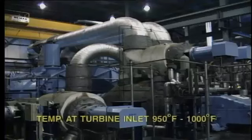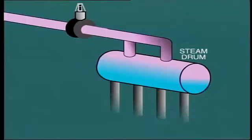For this application, the steam temperature typically should be 950 or even 1,000 degrees Fahrenheit, whereas the temperature of saturated steam is more likely to be about 550 degrees Fahrenheit, depending upon the actual boiler pressure. So clearly, for many applications, the saturated steam needs to be superheated. You'll remember we discussed this subject in the previous video in this series.